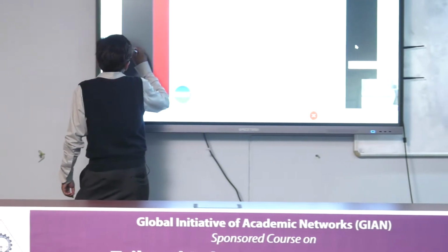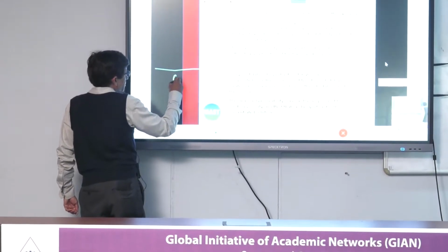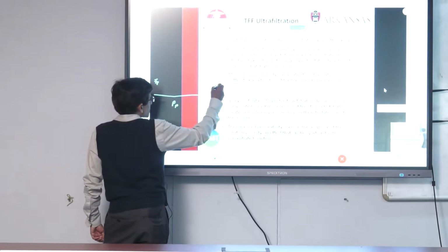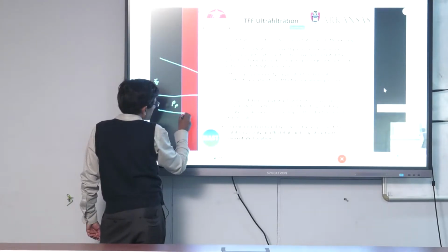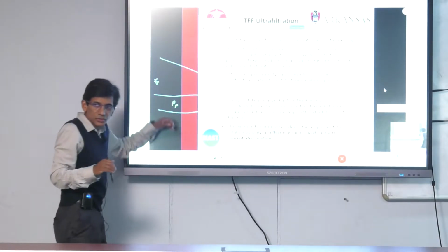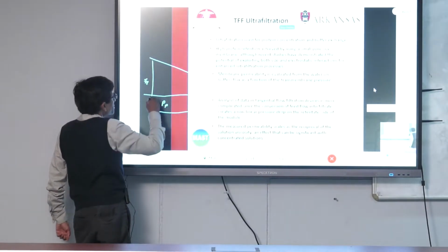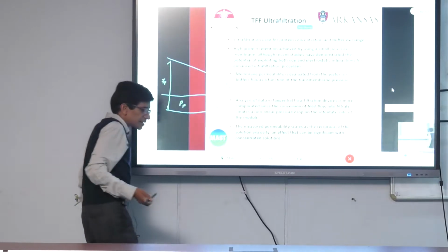So what I said was that basically, if we look at a membrane like this, we have a permeate side pressure, a feed pressure here, and a retentate pressure, and typically the pressure drops like this. The permeate side pressure is approximately constant, right? It's also going to drop a little bit if you're flowing that way, but it's approximately constant. But the transmembrane pressure drop here will be different to here, and we usually use an average.